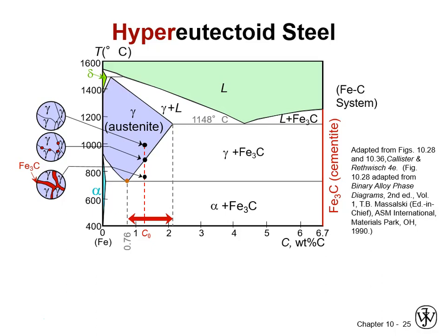That red cementite is now coating completely the austenite grains. We now have a very brittle material as the continuous phase. This is one of the reasons why high carbon steels have to be used with caution. This material would be something to be cautious of from a fracture toughness standpoint because of the presence of that continuous cementite phase. And whether or not it had enough fracture toughness for a given application would be mainly dependent on how thick that layer was, and whether or not a crack traveling through it would be in plane stress or plane strain. So see, all these concepts suddenly come to bear.